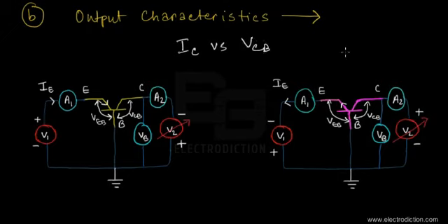It is of course required to maintain the emitter base junction over here at a forward bias voltage. So maintaining that at an optimum forward bias voltage, we can go on varying the collector base bias voltages in order to note the changes in the amount of collector current.